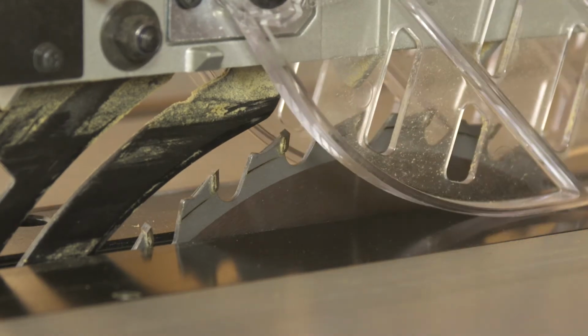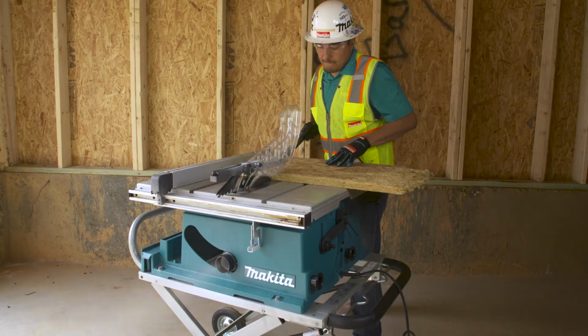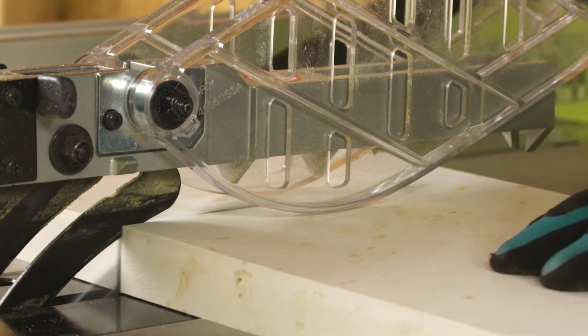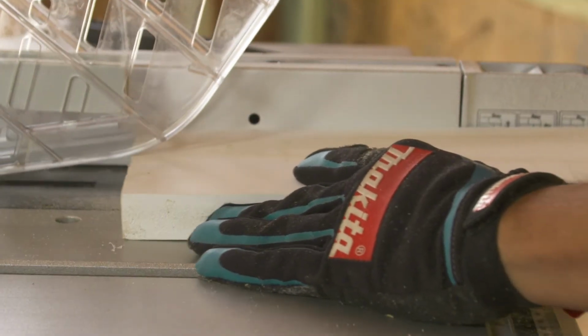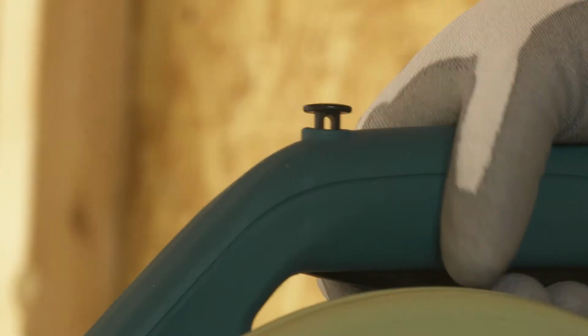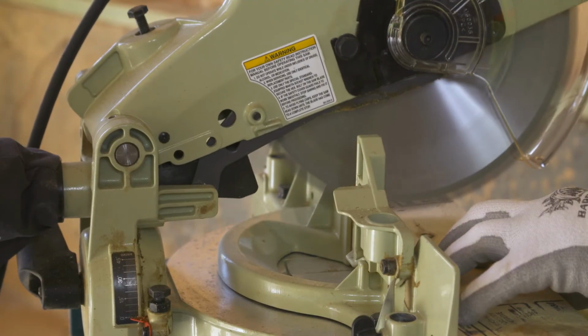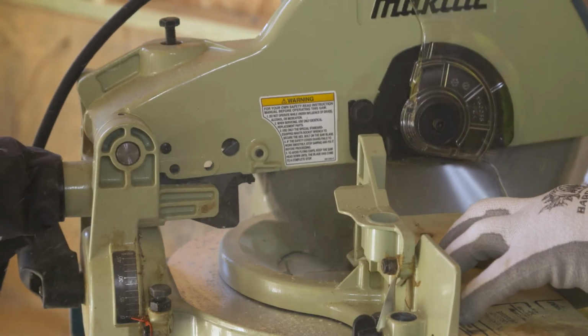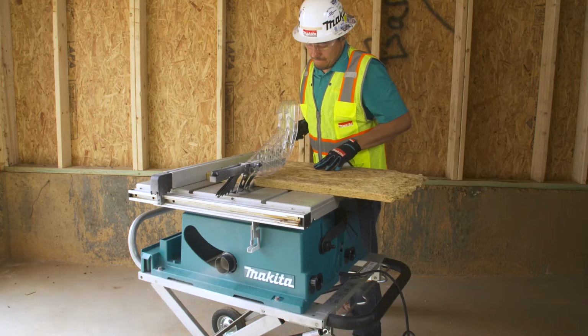Equip the saw's blade with a self-adjusting guard that adjusts to the thickness of the material being cut and that will remain in contact with it. Never remove or override any safety mechanisms built into the saw, and ensure all proper lockout/tagout procedures are followed when not in use. Be aware of kickbacks.